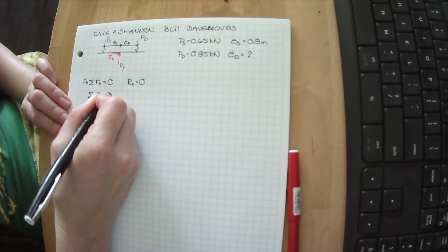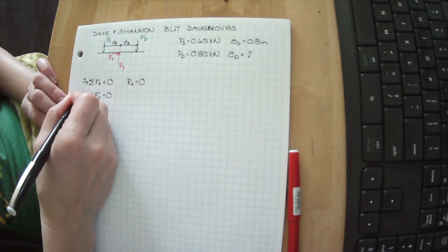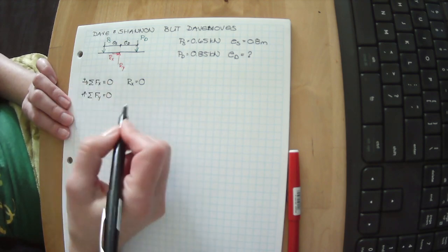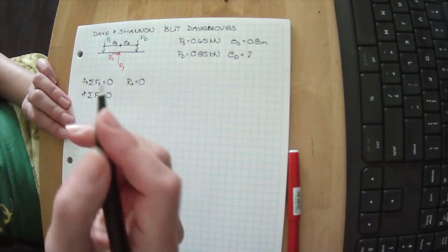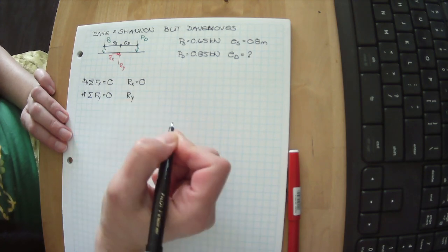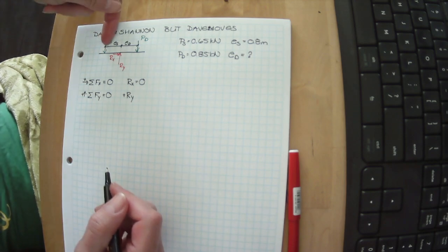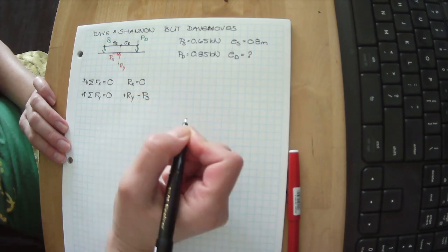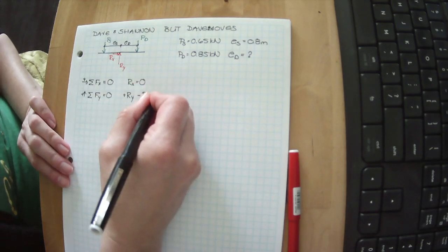Let's see what it takes for this to be in static equilibrium in the y-axis. And a reminder to ourselves that everything upwards is positive. Well, our y, our unknown reaction, we've drawn it pointing upwards. That seems like a good place to start. Our y is pushing upwards. PS, or Shannon, is pushing downwards. That's negative, so minus the force of Shannon. And Dave is pushing downwards, which is negative.